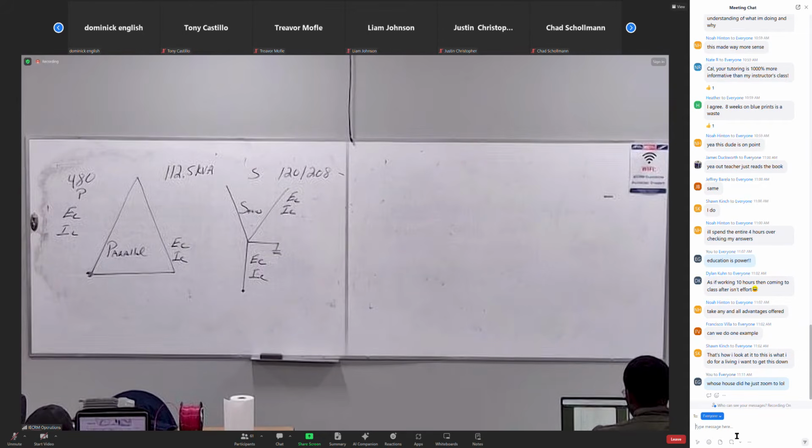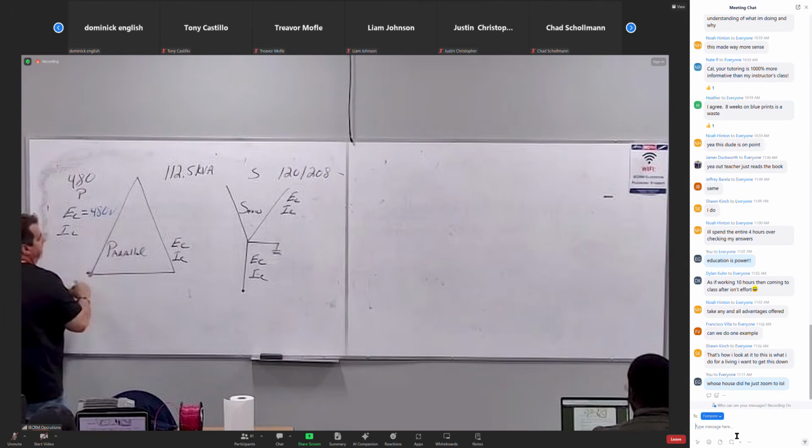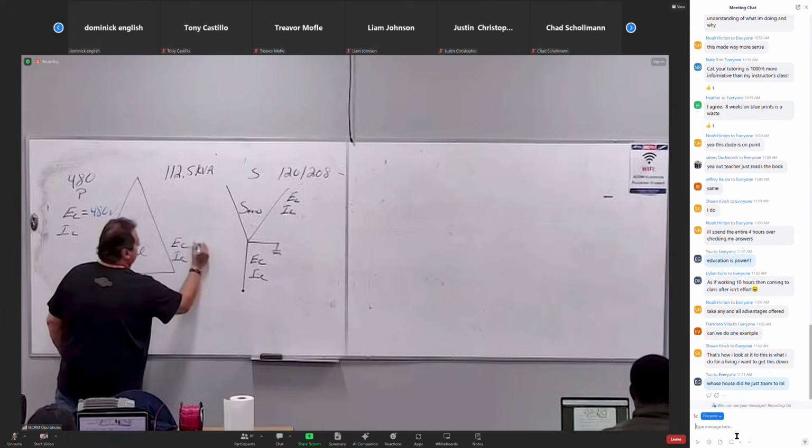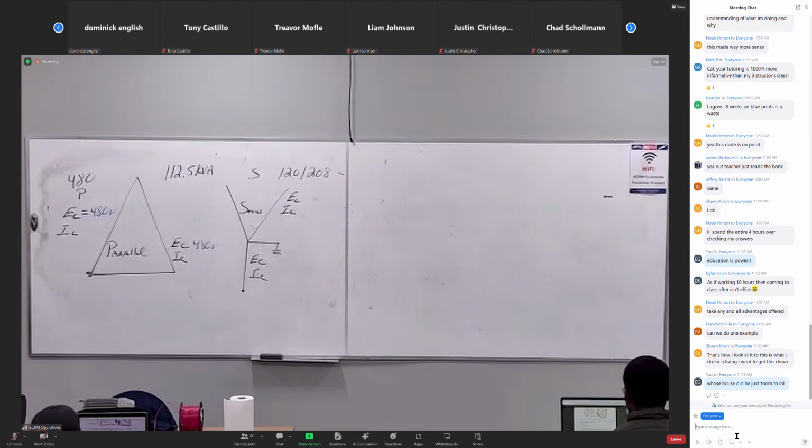Primary is what type of circuit? Series or parallel? Parallel, that means voltage does what? Stays the same. So I know that my voltage applied is 480 volts. And that means that my coil voltage is 480 volts. Okay? Here's what I want to make sure that you understand.